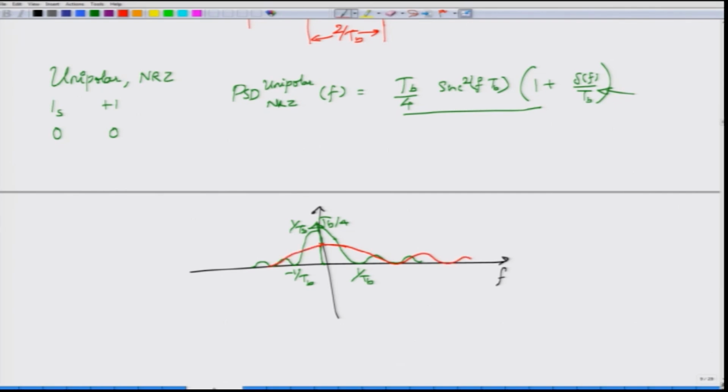Okay. So, you have a width of 2/Tb, and interestingly you also get a sequence of impulse functions. So, you get one impulse here, one impulse here, and then one more impulse here, and so on. You get one impulse every 1/Tb, and then you get something at 3/Tb, not exactly over here. So, you get an impulse at 1/2Tb, this is 2/Tb, this is 3/Tb. So, this is where you get one more impulse, okay, here.